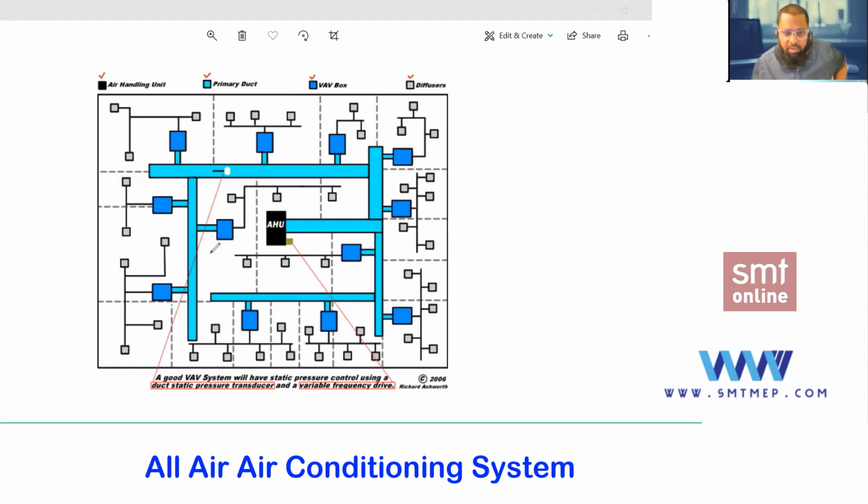So the first difference here, you see this AHU with a VFD drive, variable frequency drive. You know what a VFD drive is? Already explained in chapter 5 at the time of the VRF or VRV system, right? The VFD drive is applicable for the compressor, fan motor, and also for pumps, which you will find in module 3 at the time of pump selection. So VFD drive means by default it is a VSD, variable speed drive.